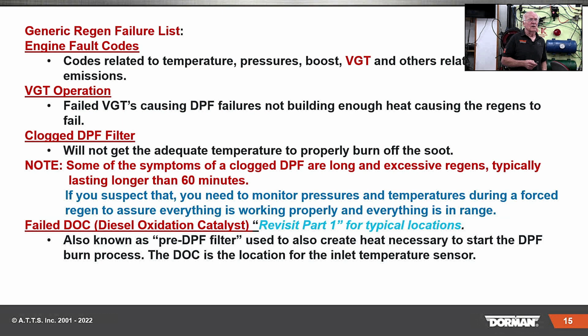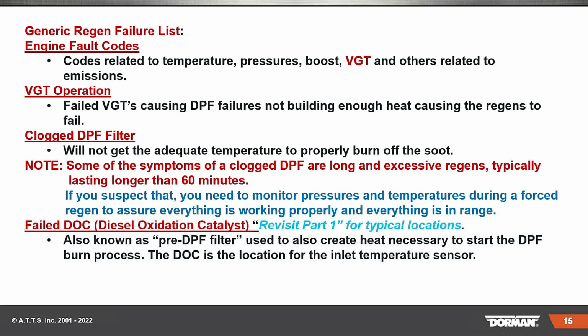Generic regen failure list: engine fault codes, codes related to temperature, boost, pressure, VGT, and others related to emissions. The thing with that, I see that debate between technicians. I'm curious what the risk is. It's not necessarily a risk, but you're in the middle of trying to figure out what's going on in there. If you can't get into a regen, and I have a picture of, for example, J-Pro, who does a real nice job over there, because don't forget who's doing the regen. Your computer's doing the regen.